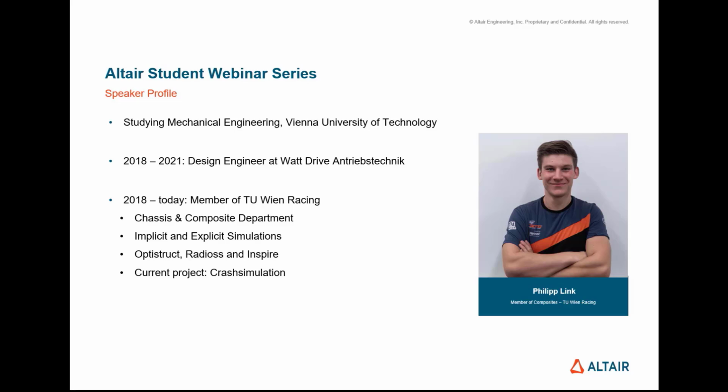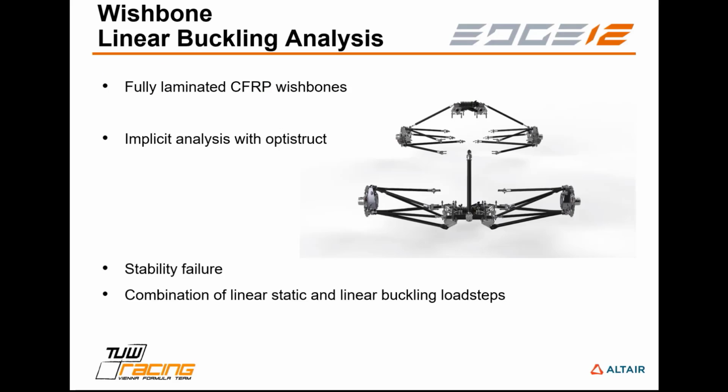Hello, and welcome back from my side. Now we're going to take a closer look at a simulation very relevant to our suspension department. I'm talking about linear buckling analysis of our fully laminated carbon fiber wishbones. During the development process of our wishbones, we do multiple implicit analyses with OptiStruct, and for this session, we're going to focus on the stability failure resulting in buckling of those hollow wishbones.